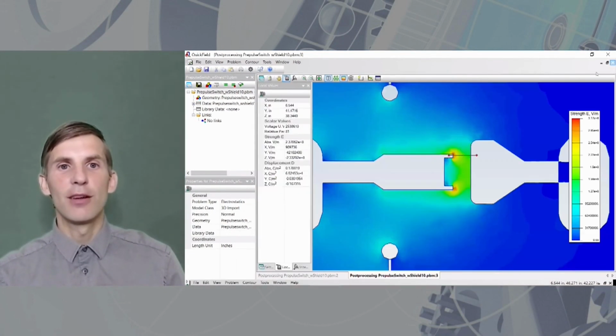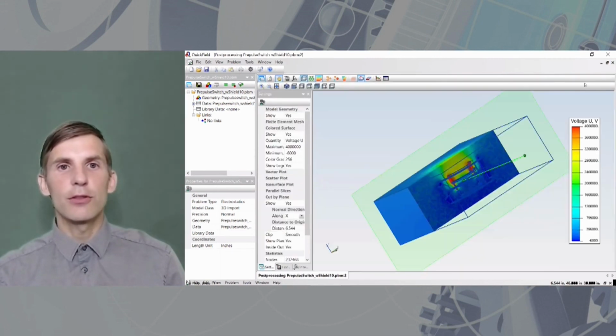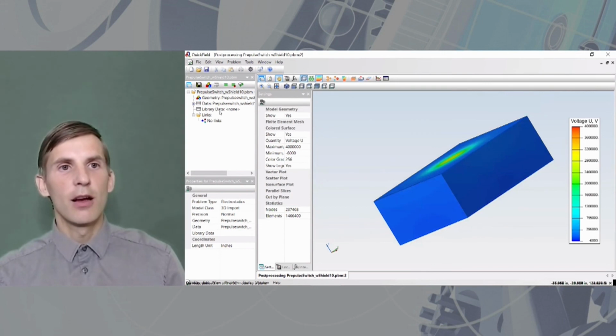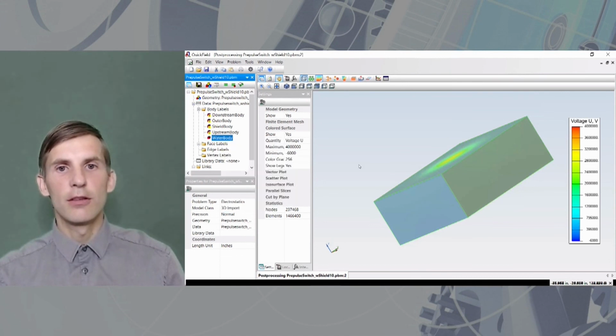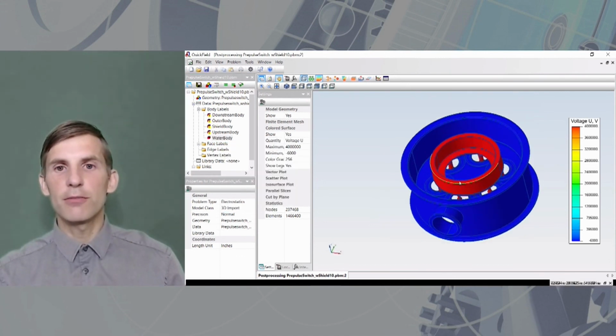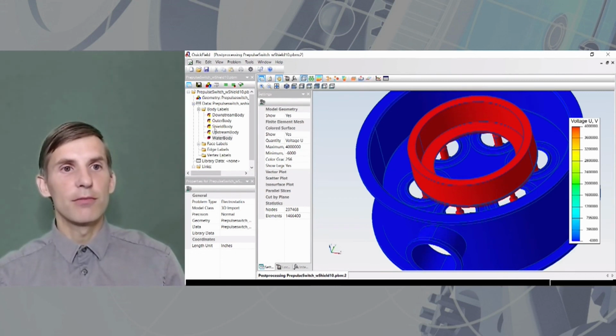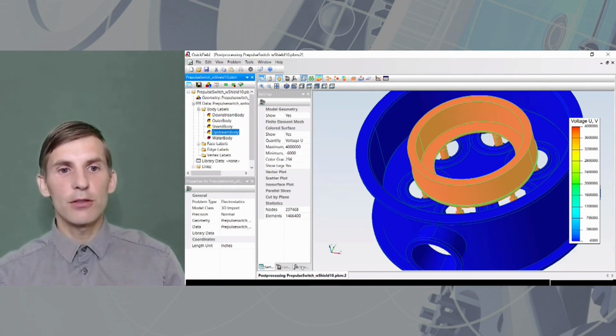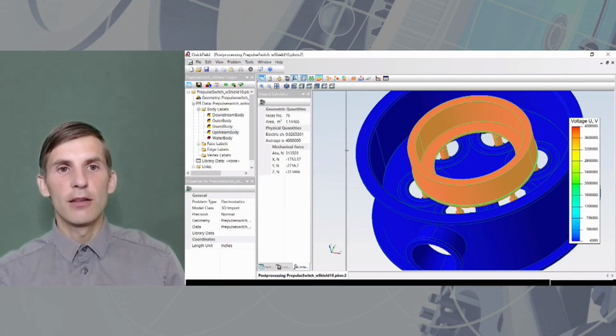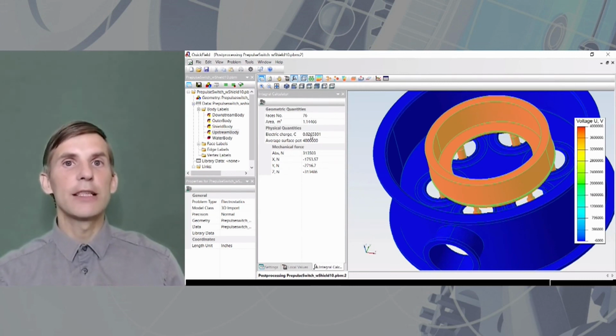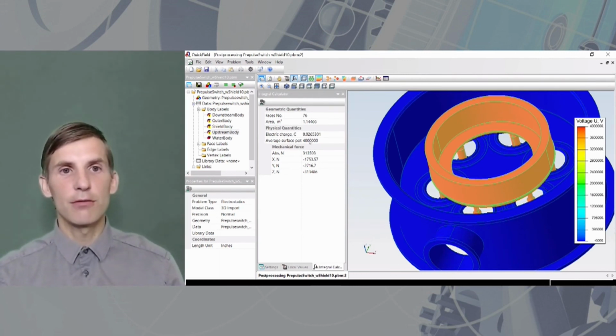Okay. Close this window, close this window. I will hide the water block. Now you can see the electrode system. To calculate the capacitance, I need to find the charge. That's easy. I select upstream body, follow to the integrals, and this is the electric charge. If I divide the charge by the potential difference, I will get the capacitance. That is how it is done in QuickField.